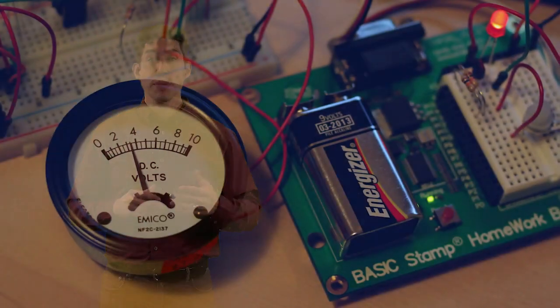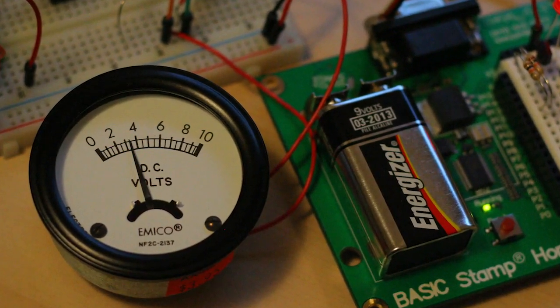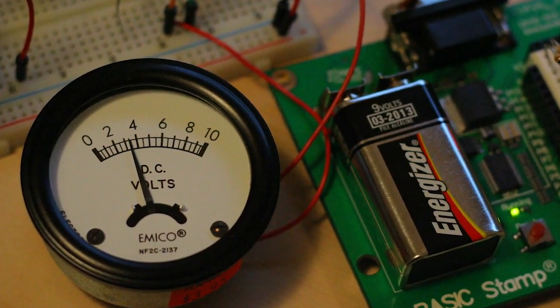Jumping right in, voltage, which is the system potential, needs to be measured outside the circuit. We do that using a voltmeter. A voltmeter essentially has infinite resistance, so no current flows through it. Current, which is the other measurement, is measured in line, so electricity will actually flow through the meter. This can be potentially unsafe or difficult to do in practice.